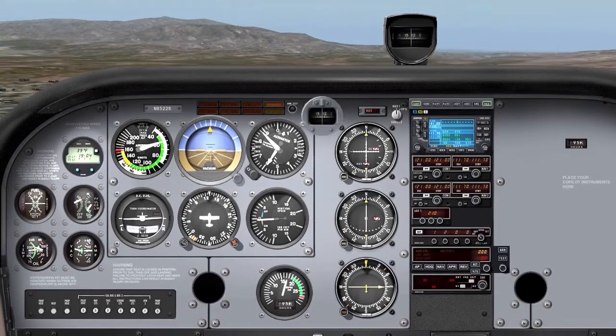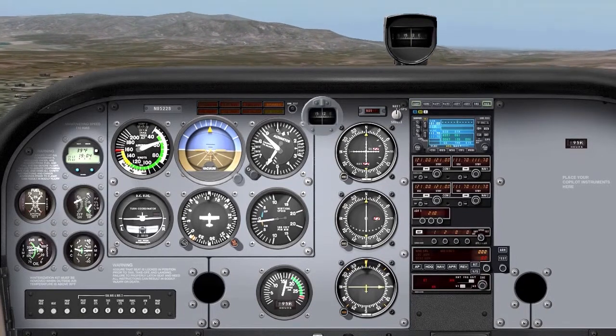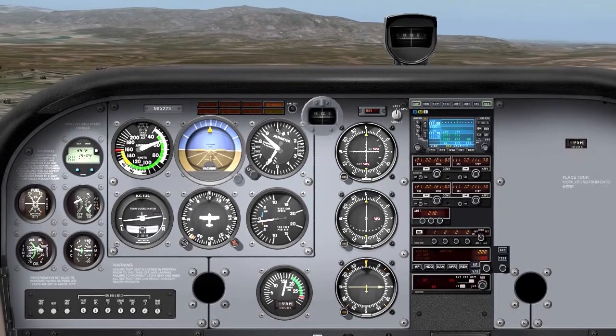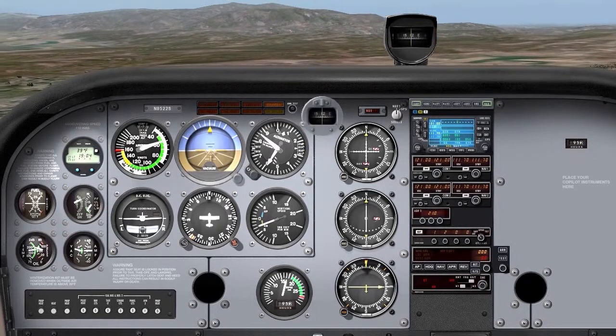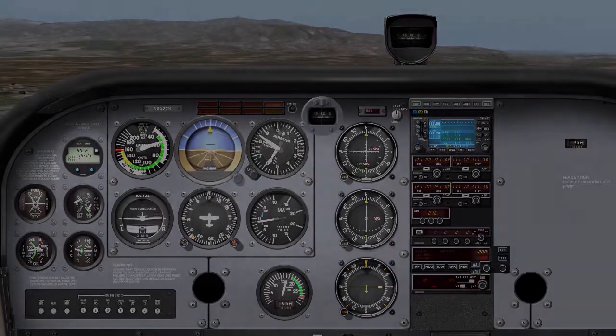After the airplane has achieved sufficient airspeed, it can be returned to normal, straight, and level flight. The stall usually occurs when the pilot uses abrupt input to return to straight and level flight. With smooth control of the airplane, the secondary stall can be avoided altogether.